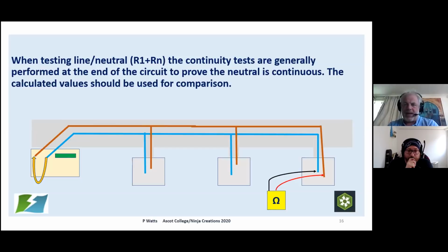And you've got to look at the individual circuits, how many times they're connected to the trunking, at what points, and how many circuits you've got in that, and how that overall effect is going to be. Remember, you've got one set of trunking or one set of conduit. It's a nightmare of a calculation to avoid. It's really quite difficult, and from a practical point of view, I don't see how anybody can accurately calculate what that value should be, allowing for the multiple parallel paths within the trunking and the conduit system. I just don't see it.